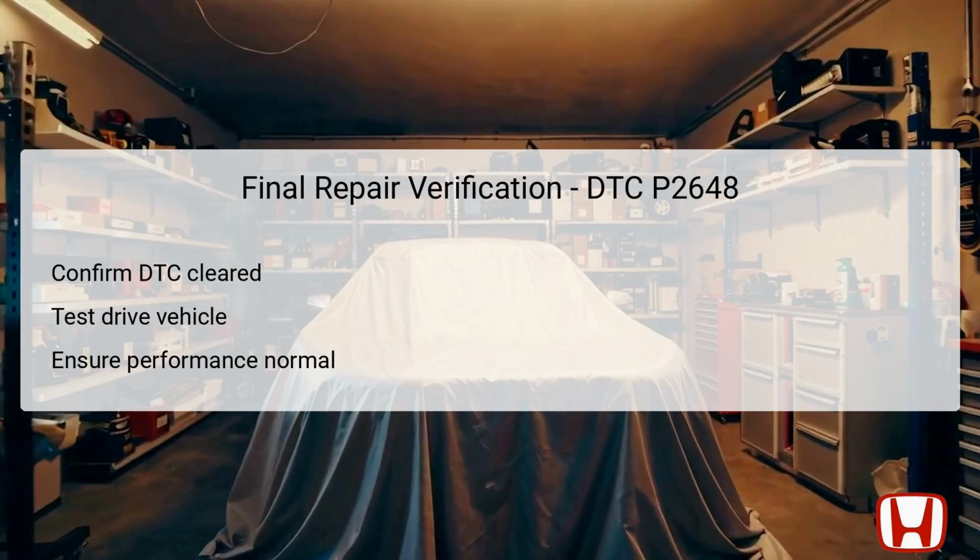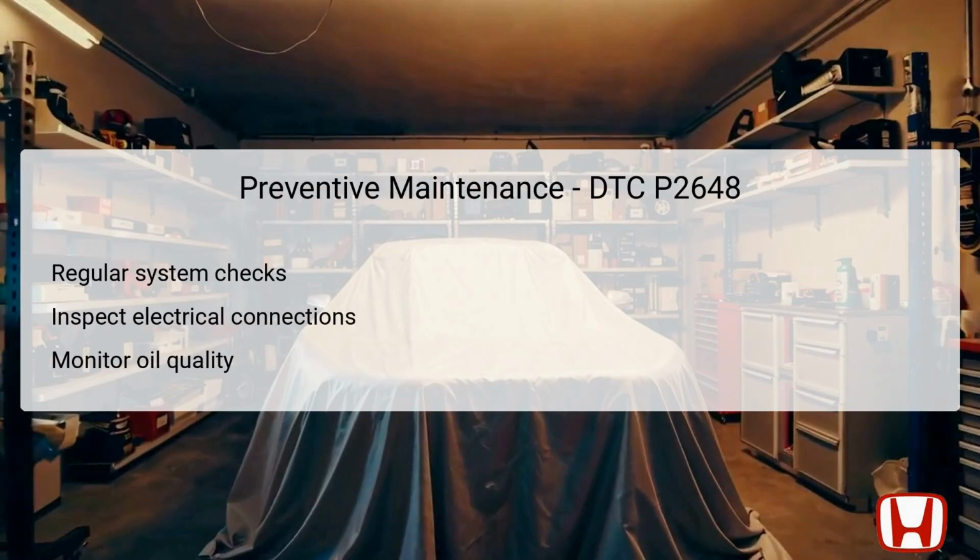issues were overlooked. Preventive maintenance plays an essential role in avoiding DTC P2648 and ensuring the longevity of the rocker arm oil control solenoid system. Implementing regular system checks can help identify potential trouble before they escalate. This includes periodic inspections of electrical connections, the connectors at the rocker arm oil control solenoid and PCM, ensuring all contacts are clean and secure.